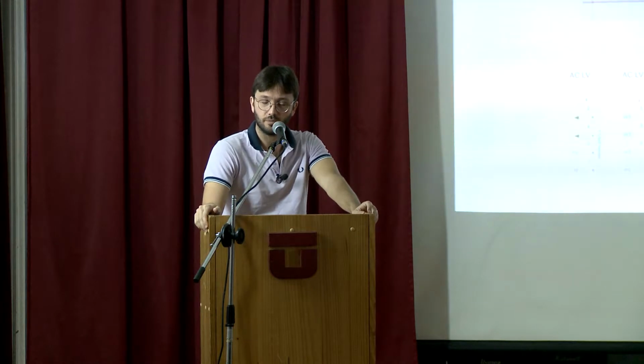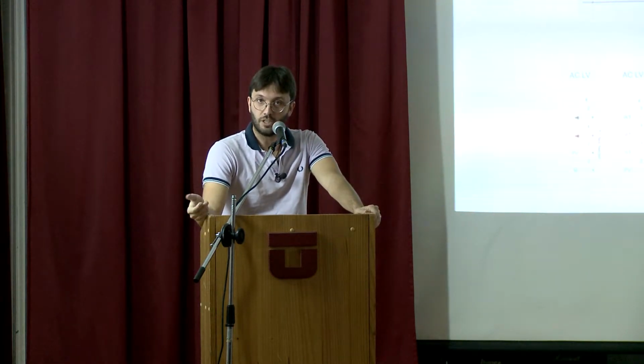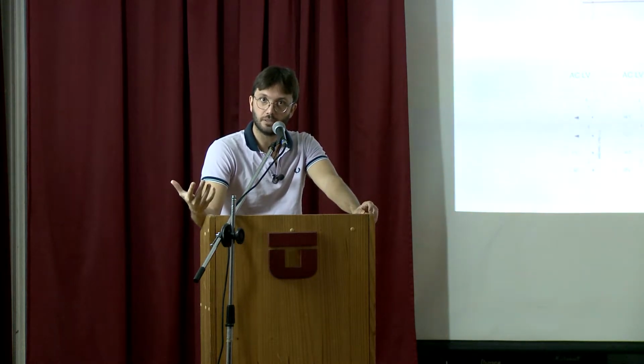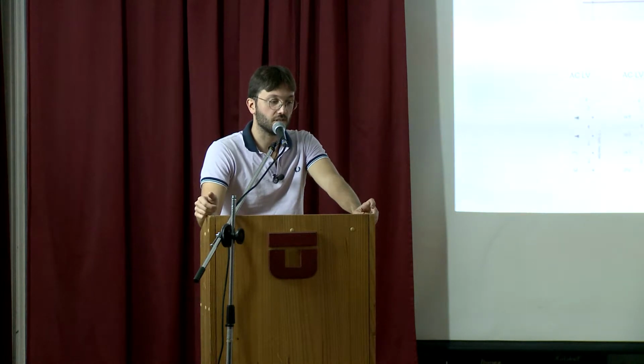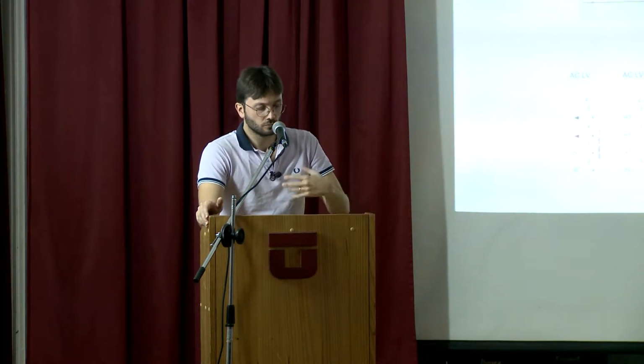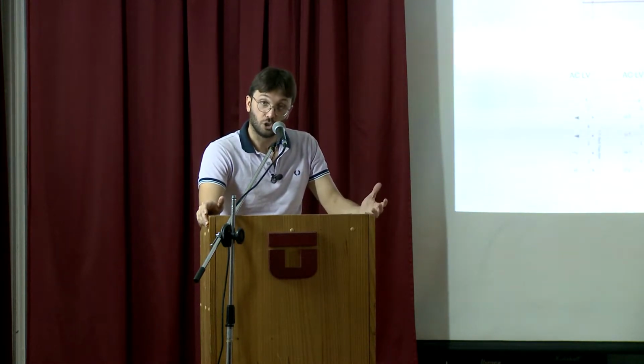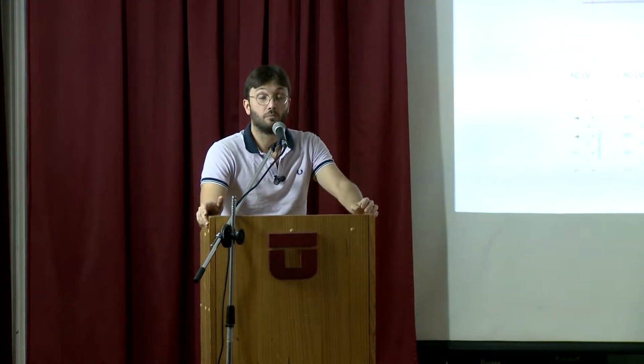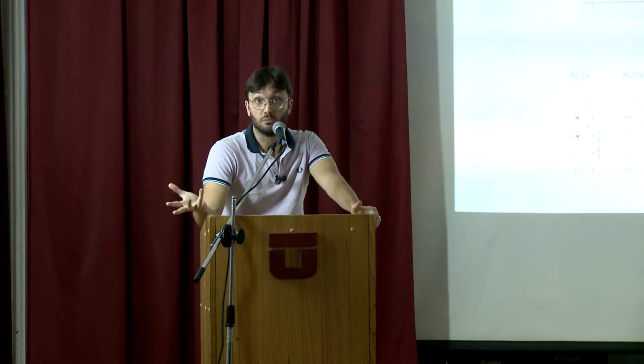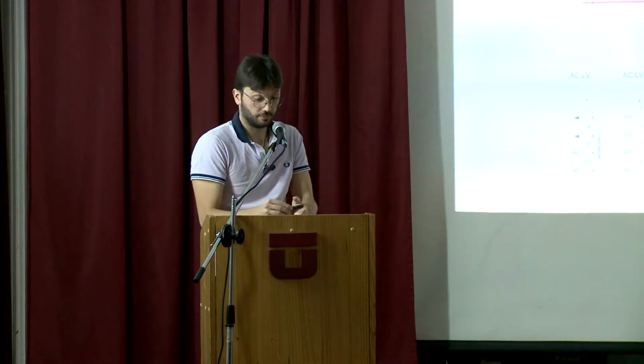No, it's fine. So the grid, in a weak grid, so weak means with a high impedance, is really sensitive to these nonlinear and harmonic loads. So you're expecting to see some sinusoid, actually you see something with third, fifth, seventh harmonic. So it would be already a good service offered by the solid-state transformer, the power quality control and power quality improvement in the low voltage grid.